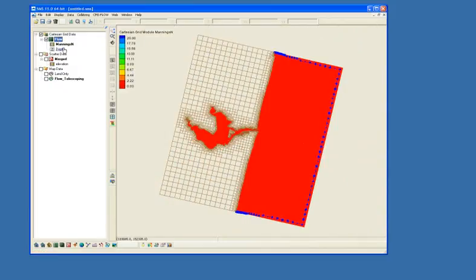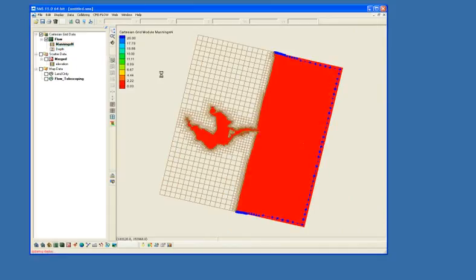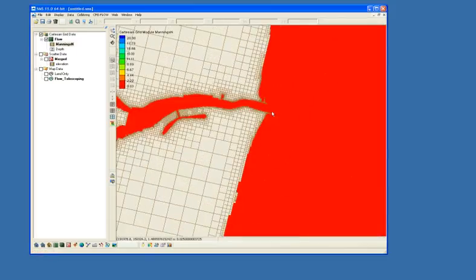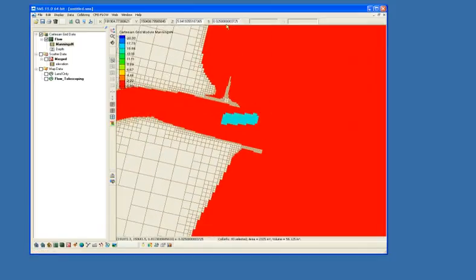All right, so now I can look at the depth or the Manning's n. I can select cells and see the values here. If I want to modify these values, you would select cells in whatever location you wanted to modify the Manning's n and change the value in the S or scalar entry blank. You don't want to mess with the Z because that's your depth. Even though you're selecting Manning's n, if you change this Z value, it's going to change the depth value. So that's how you would modify the Manning's n for this particular one.